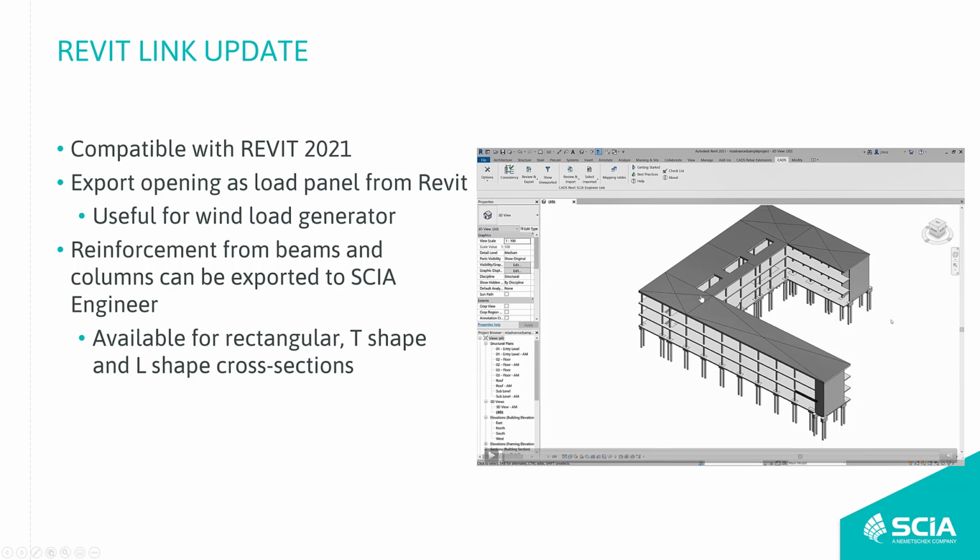Here you can see that I have an opening and I can just run the export of a model, and in SCIA Engineer I will get the opening filled by a load panel. That's useful in the case of the 3D wind load generator, where I can simulate that it's a window, or a door in the case of a wall.